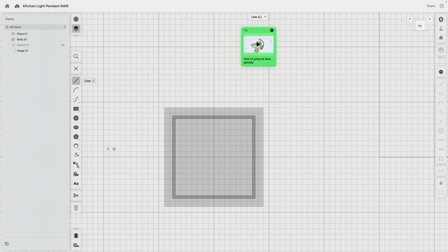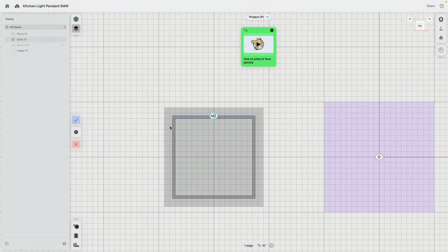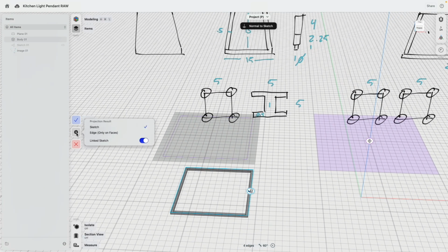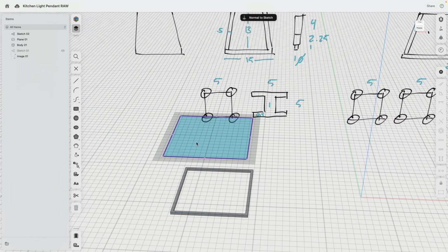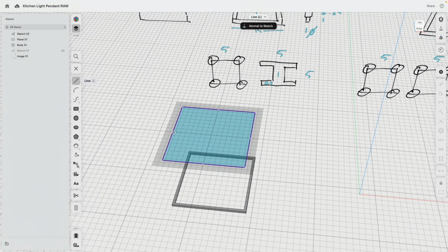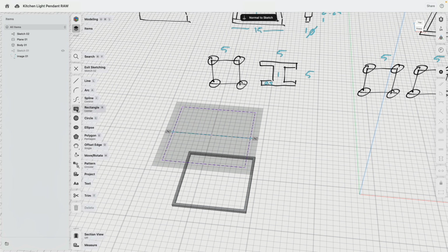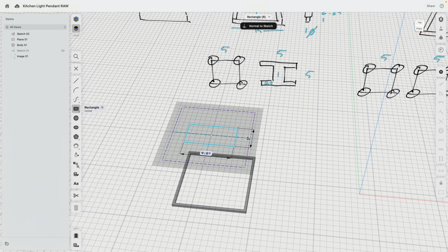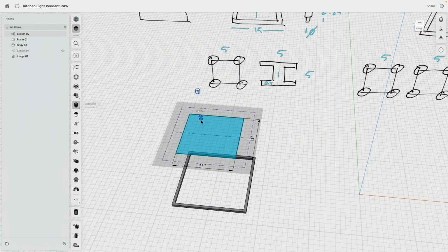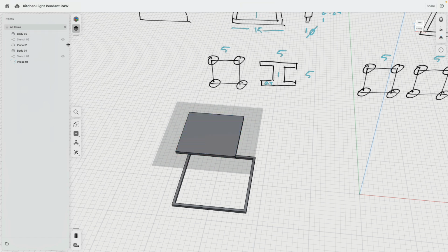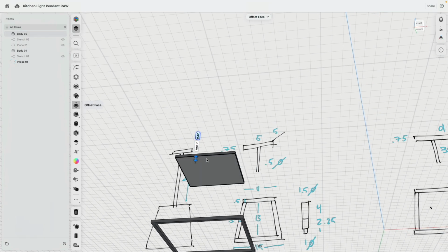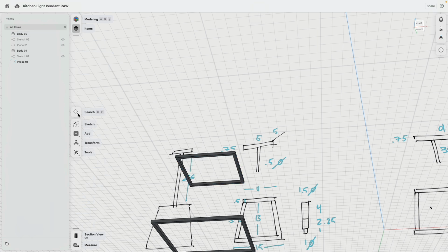The grid perfectly lines up, but to be clean, let's actually project these edges into the sketch. The main reason why I then can draw here one line, edge to edge, escape, select everything. That's a construction line, and I have a midpoint. Then I can make a rectangle 11 by 11, enter, there we are. Select the sketch, 0.5, hide all the sketches, and then we do the same and shell 0.5.